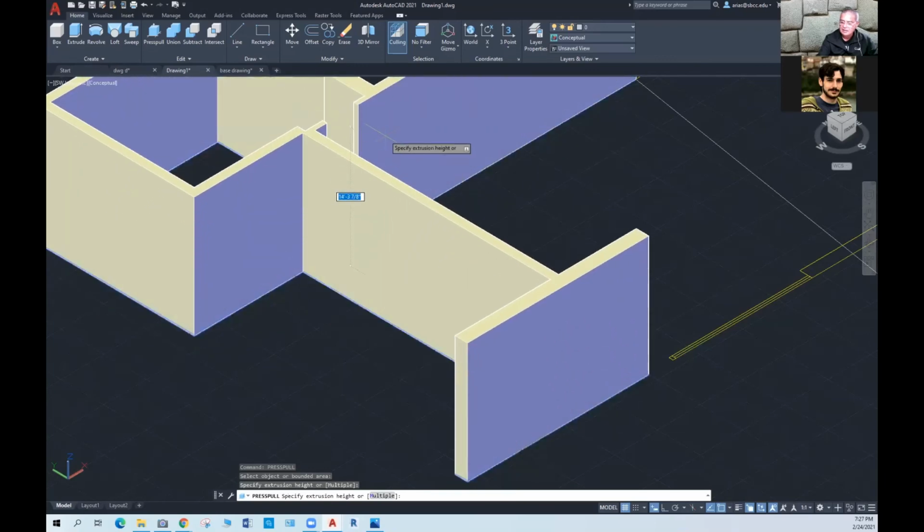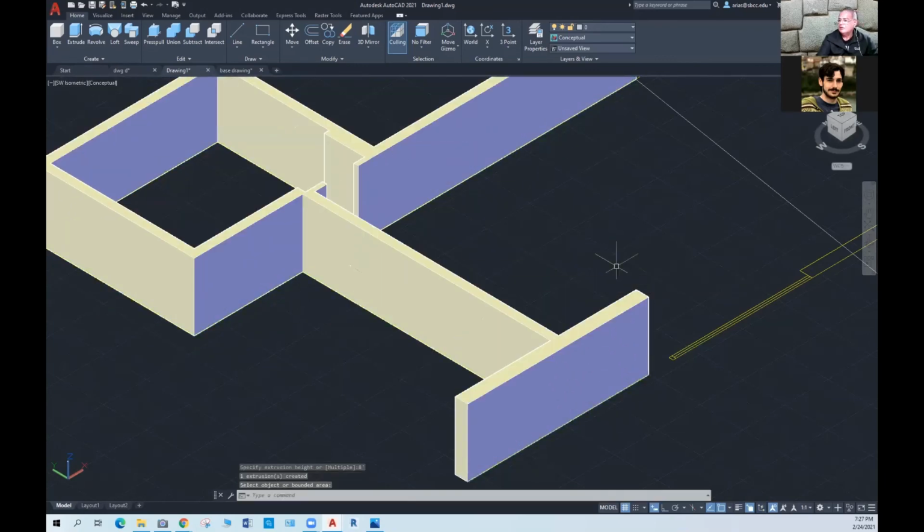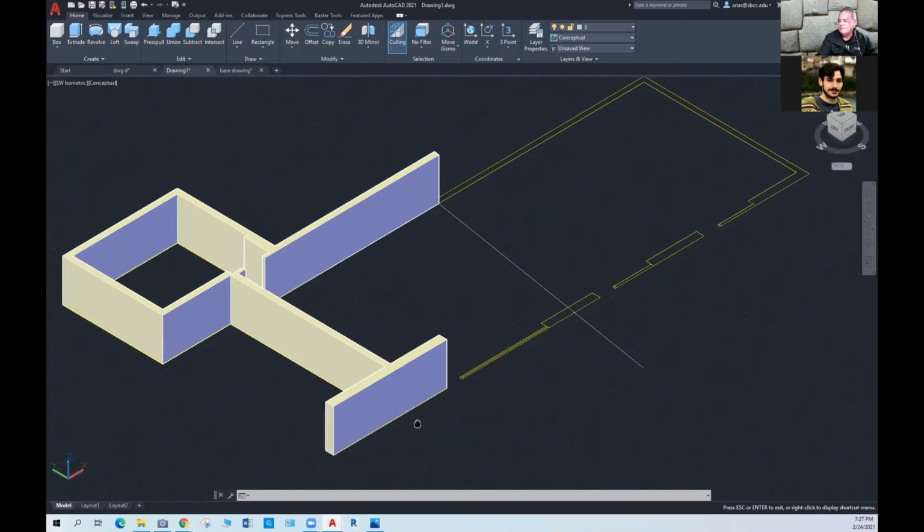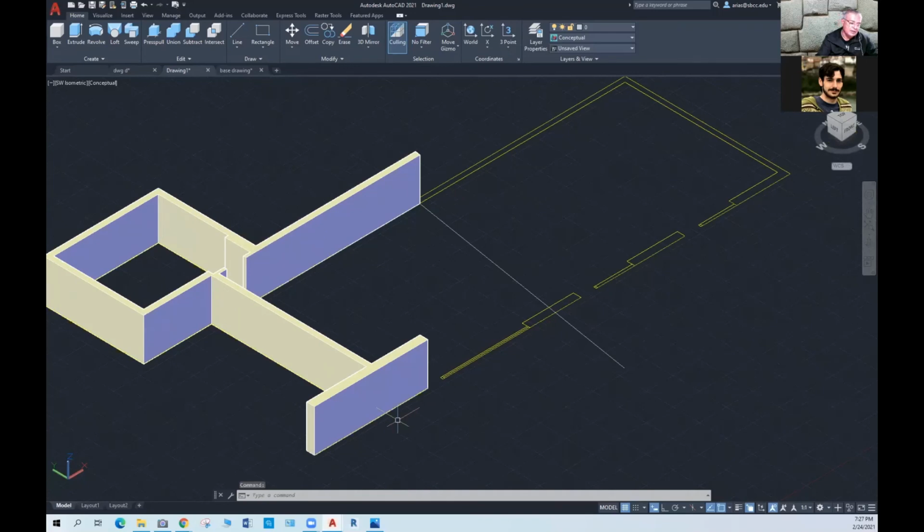Now I have it, and now I type 8 feet. And so see, I can do that. I can do the whole thing right away. That's one thing. So maybe that's something you can do also, if the floor plan that you have allows you to do that, then great, then it's all good. And so we're going to see other tools that we can use as well to create the geometry. But for now, the use of the extrude and the use of press pull are okay.